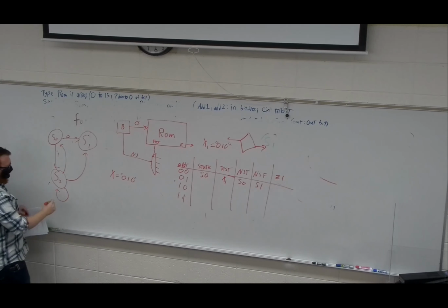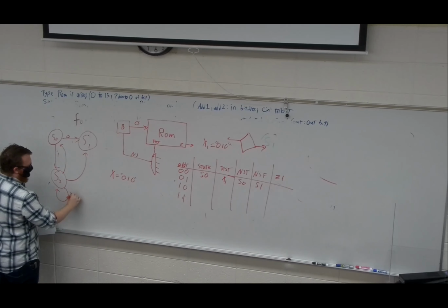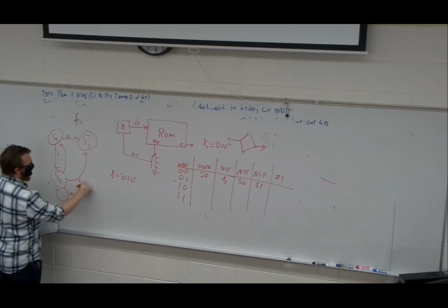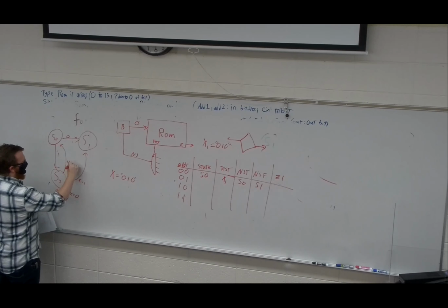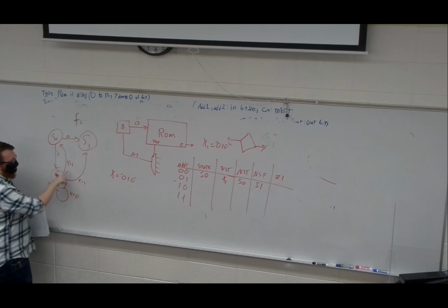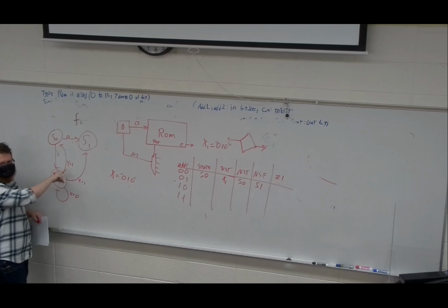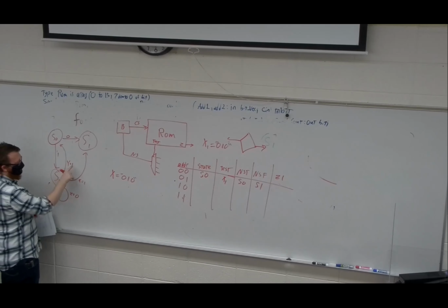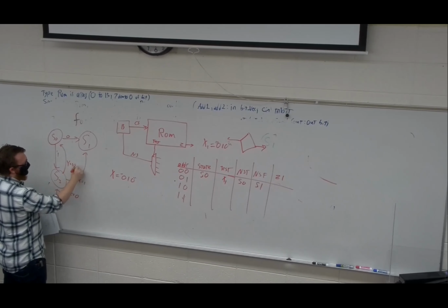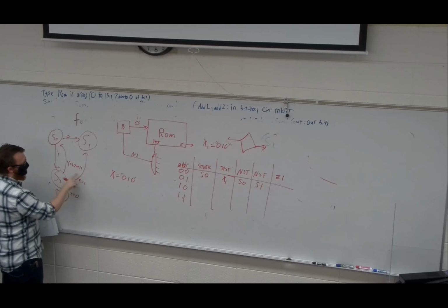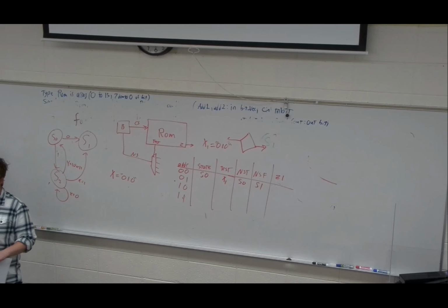Now I have, well, if X is equal to 0, if X is equal to 1, or Y is equal to 1, and you have some specification, I have to define it, right? Where it's like, well, 1, 0, or 1, 1. So Y would overtake X or something, right? I have to define my outputs and priorities. The general idea is if it has 3 arrows coming out of it, it's not microcode compatible. So I might give you a diagram and say, turn this into a state machine chart with the appropriate number of states such that it is microcode compatible.